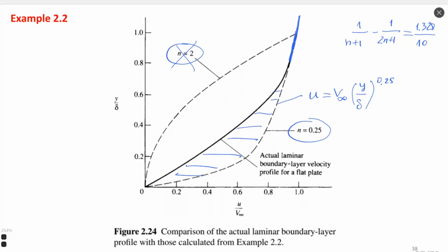We do not have a difference at the starting point, 0.0 velocity, and at the final point, where our boundary layer finishes. We also do not have error there. In all other points, we have error. This happens because of one reason, and this reason is called the control volume approach. This is one of the disadvantages of the control volume approach.